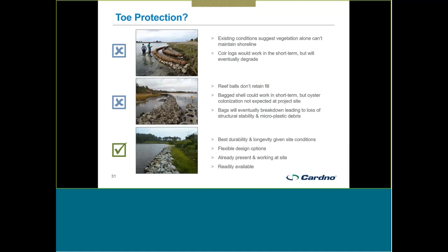So in the end, we decided that the best combination of durability and longevity would be rock in a toe sill arrangement. There was already a good example of that actually right next to our project site. You can see in this picture, this is the project site, and just on the other side of this little unpaved boat ramp, there was a toe sill-like shoreline structure already in place.